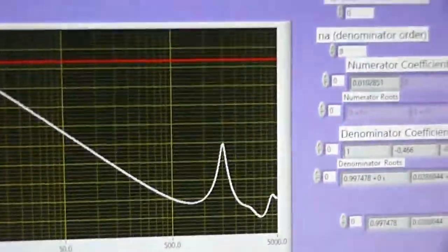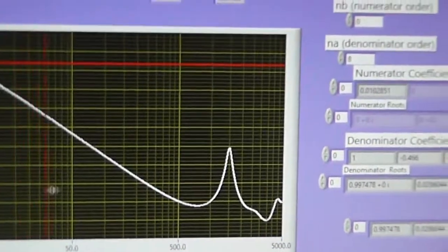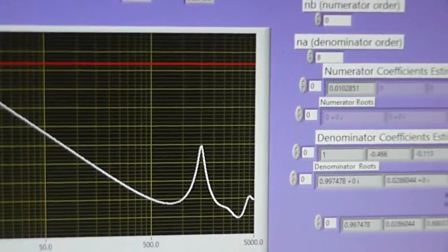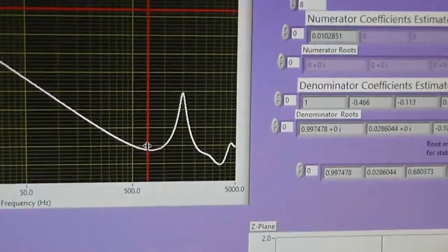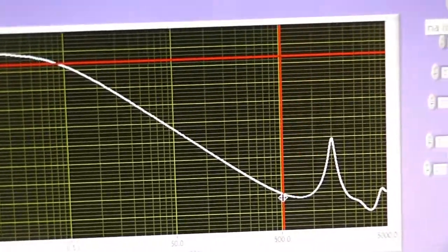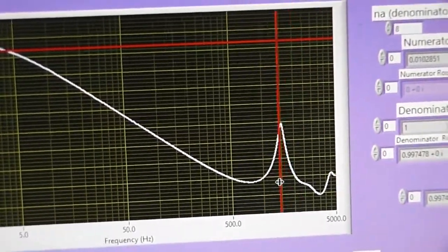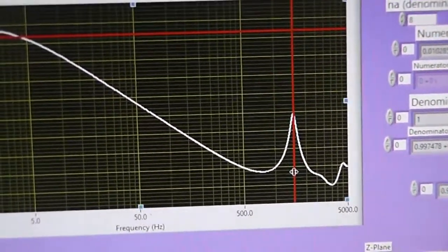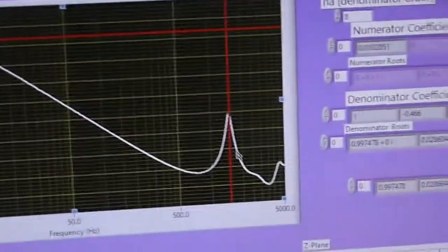The interesting thing is that you can't seem to see any effective inductance at all. It's just got the one pole all the way down to about 500 Hertz. There's not much really happening. It's just going to be K over 1 plus ST. But the beauty is that you see the structural resonance. It comes out really nicely here. Structural resonance at 1.5 kilohertz.